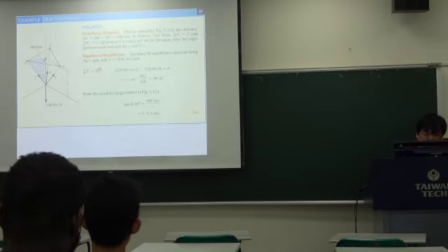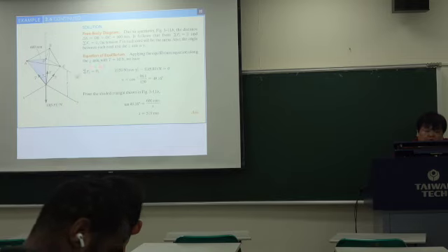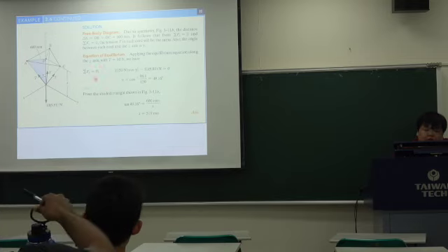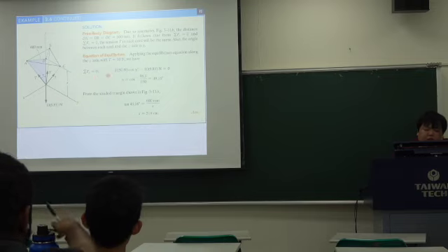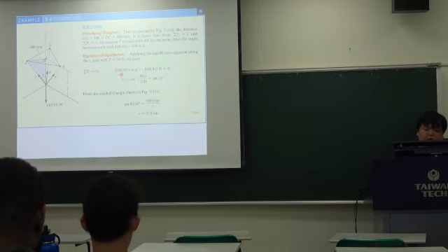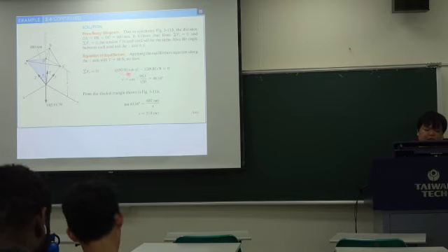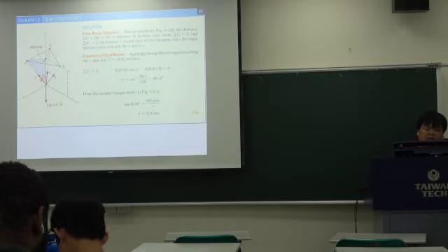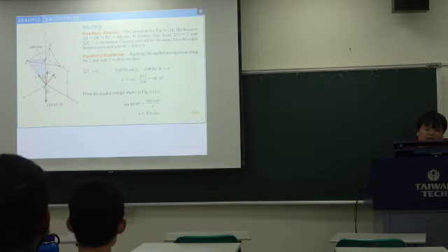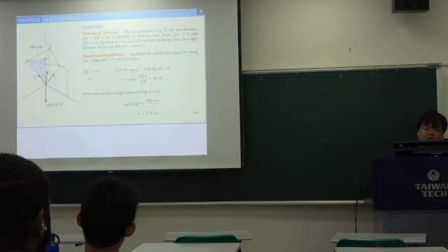So when we only consider the dimension Fz equal to 0, we just use the tension force 50 Newton times the cosine gamma. We can get the z direction force. Then because we have three poles, we multiply by 3.